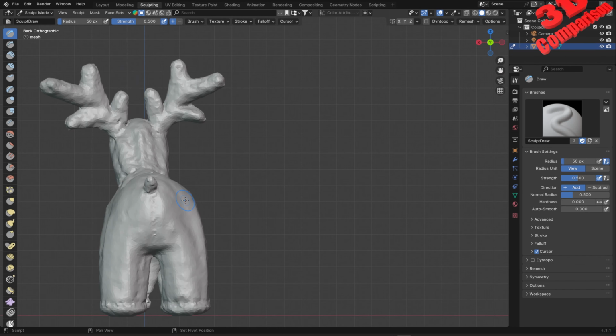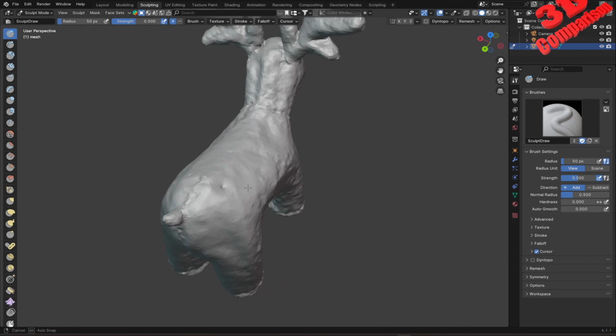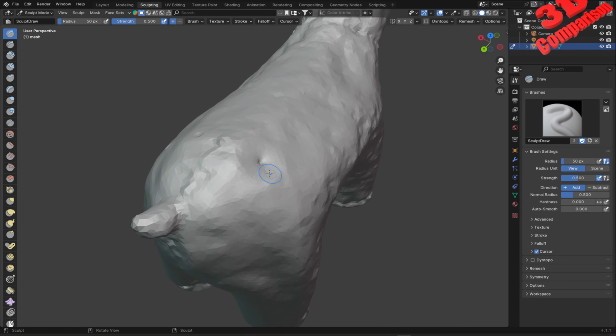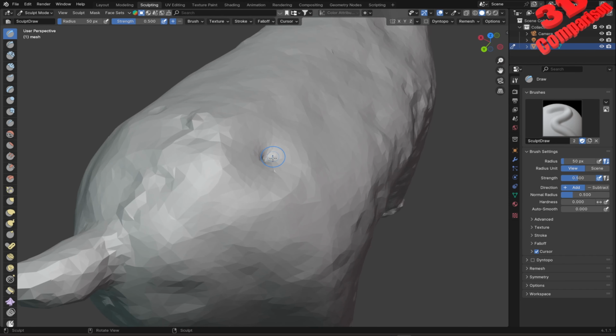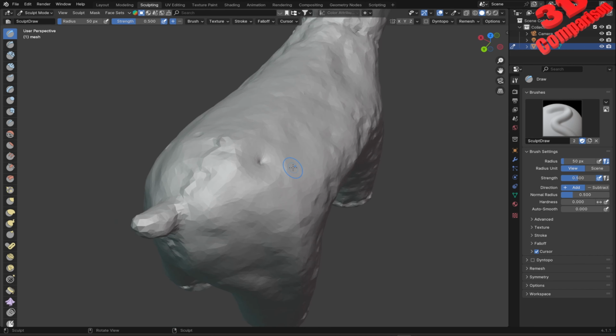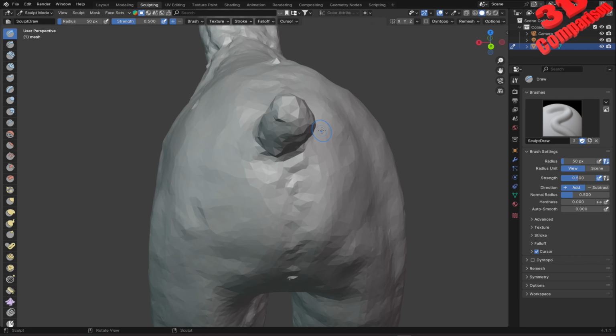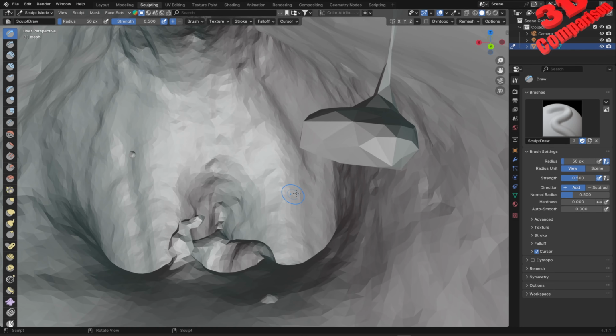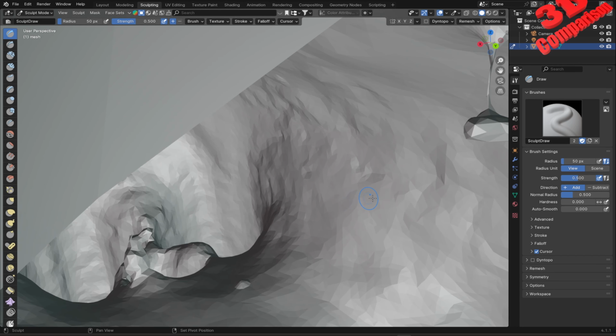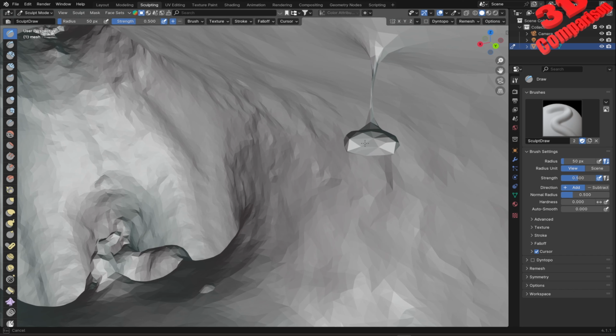Over here we see that we have some elements on the interior. If I try to smooth that, we're going to see how that will slowly change. So in this case I will need to go inwards and smooth it from the inside. So let's see how that will work. We see the mesh will have that element over here, so I have the possibility to smoothen that out.